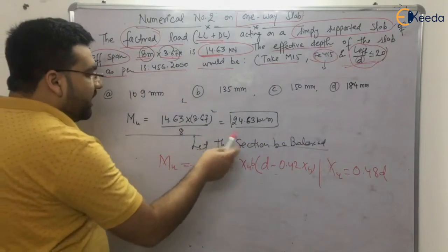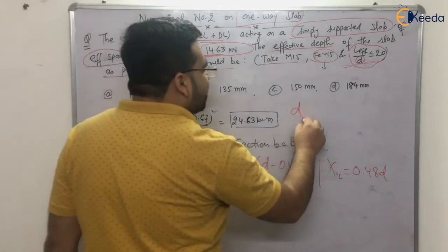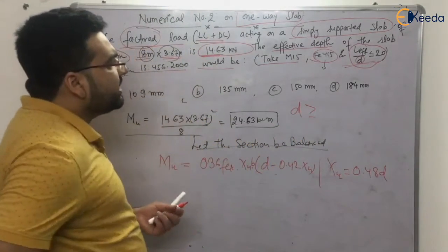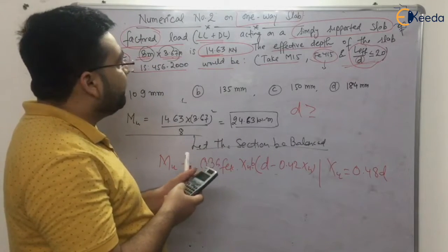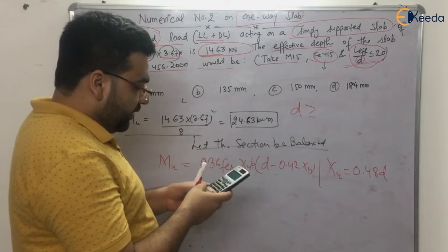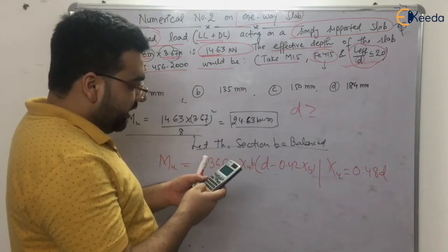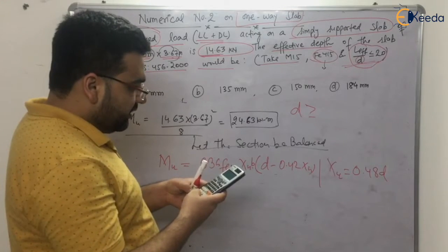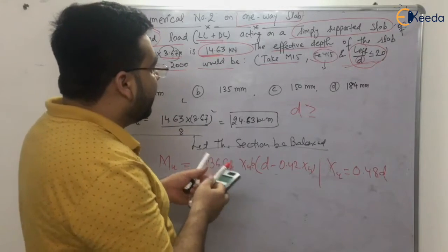Clear? Now from the first criteria, the deflection control criteria, our effective depth was coming out to be, I guess, 71 point something, right? So 3.67, we actually adopted 3.67 divided by 20, into 1000, it came out to be 183.5 mm, right? I am writing it also, right?